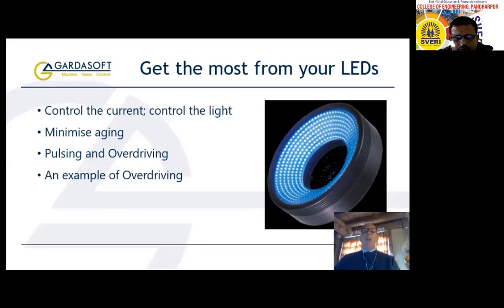Strobing an LED light brings significant benefits because when the timing and duty cycle are carefully controlled by the controller, the light can be overdriven to achieve light intensities much higher than the manufacturer's light rating. This is an extremely useful technique in many scenarios.